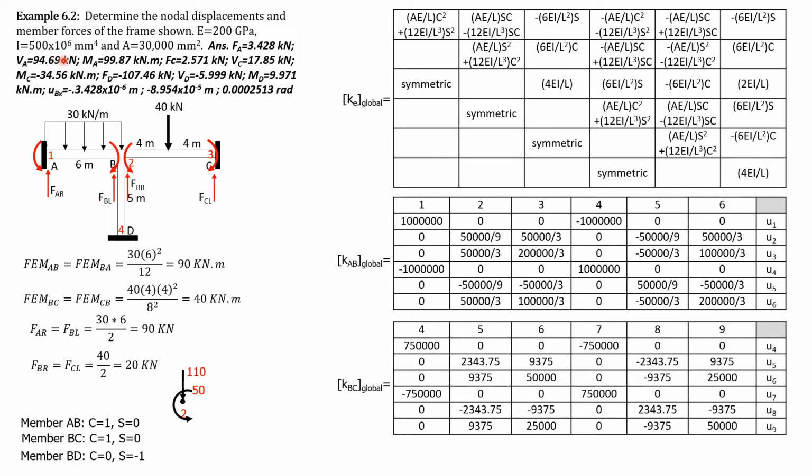Moment of inertia, you divide that by 1,000 to the fourth, so that you will arrive with these values here. So that's the global stiffness of BC. Then for BD on the next slide, you just pause, then verify these values, and you look at the displacements also.